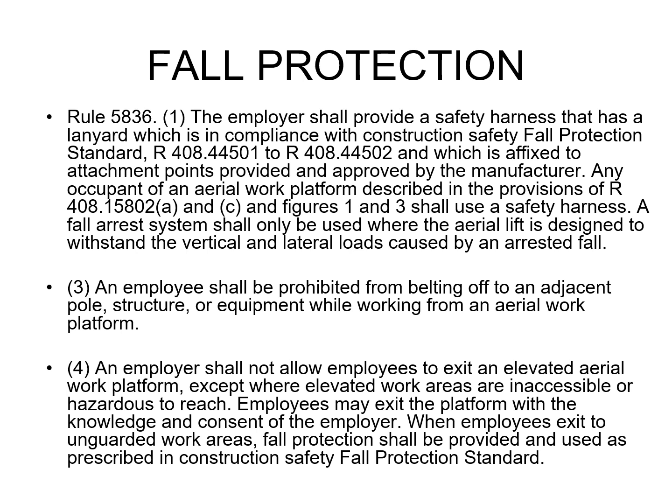A fall arrest system shall only be used where the aerial lift is designed to withstand the vertical or lateral loads caused by an arrested fall. 3. An employer shall be prohibited from belting off to an adjacent pole, structure, or equipment while working from an aerial work platform. 4. An employer shall not allow employees to exit an elevated aerial work platform except where the elevated work area is inaccessible or hazardous to reach.